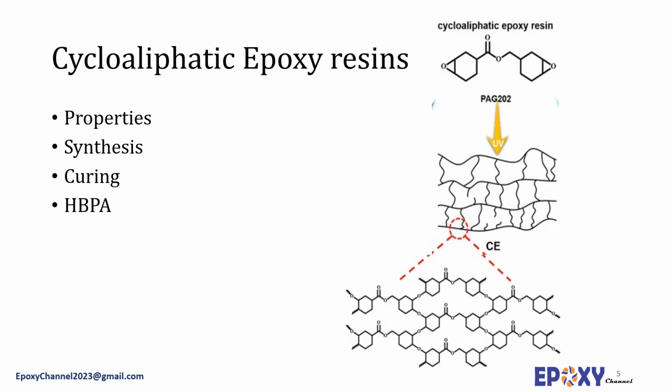Like standard epoxies, cycloaliphatic epoxies can be cured or set with a wide range of co-reactants, including polyfunctional amines, acid anhydrides, phenols, alcohols, and thiols. Regarding curing, aliphatic epoxy resins polymerize very slowly at room temperature, so higher temperature and suitable accelerators are usually required.